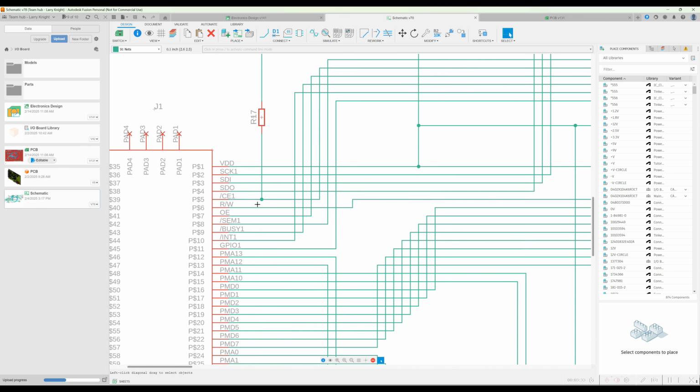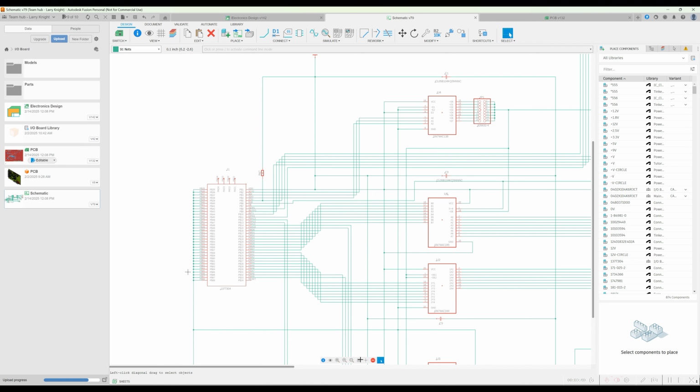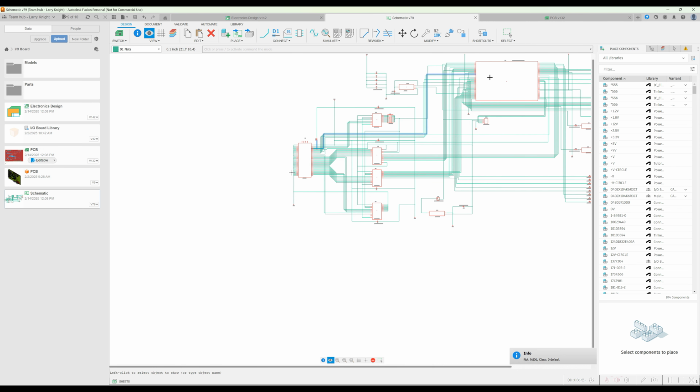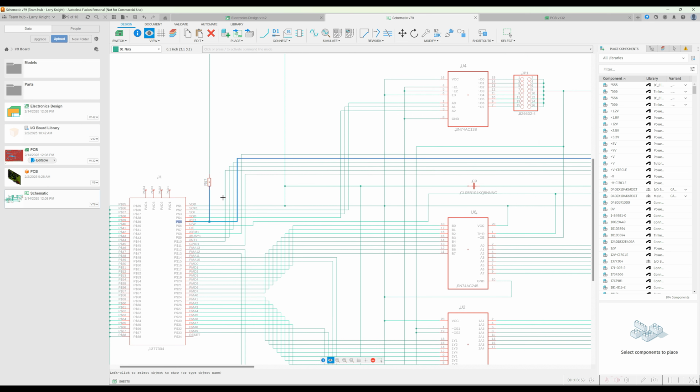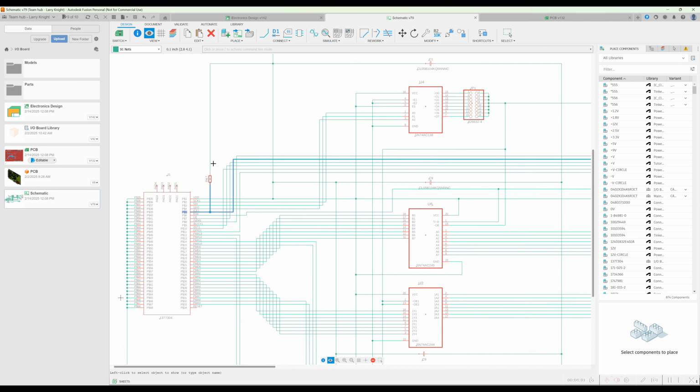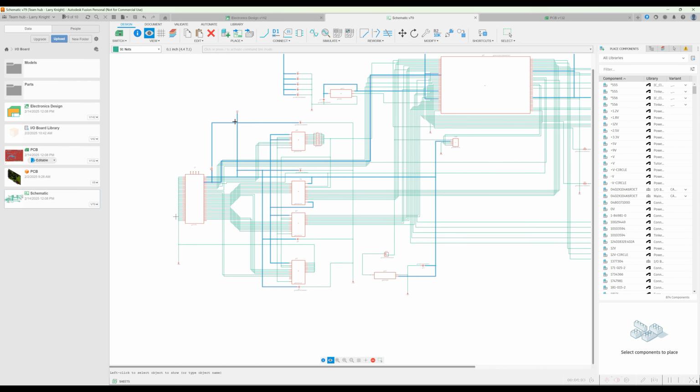We want to get that stabilized, because chip enable should not be low until we tell it to go low. And only the microcontroller does that. So there's no microcontroller, so we want that to default to a high state. And we may want to do that here, but let's get a resistor on here and pull that signal high to VDD and see what happens.